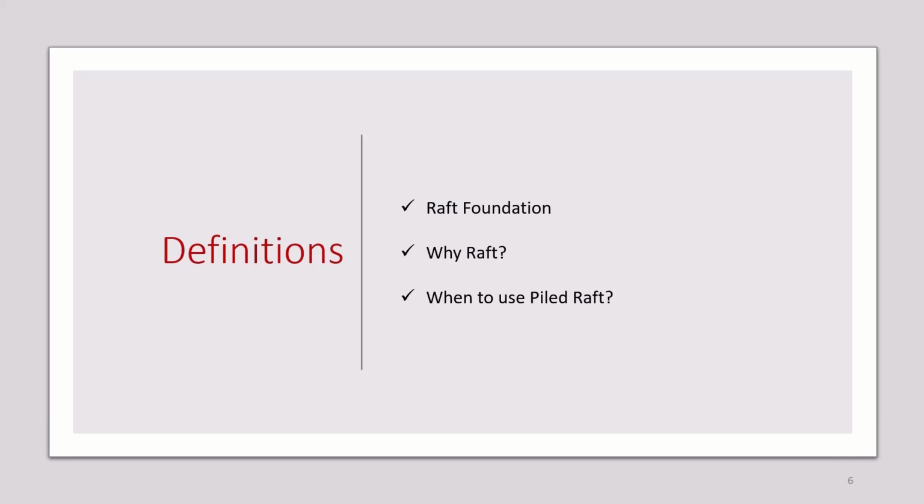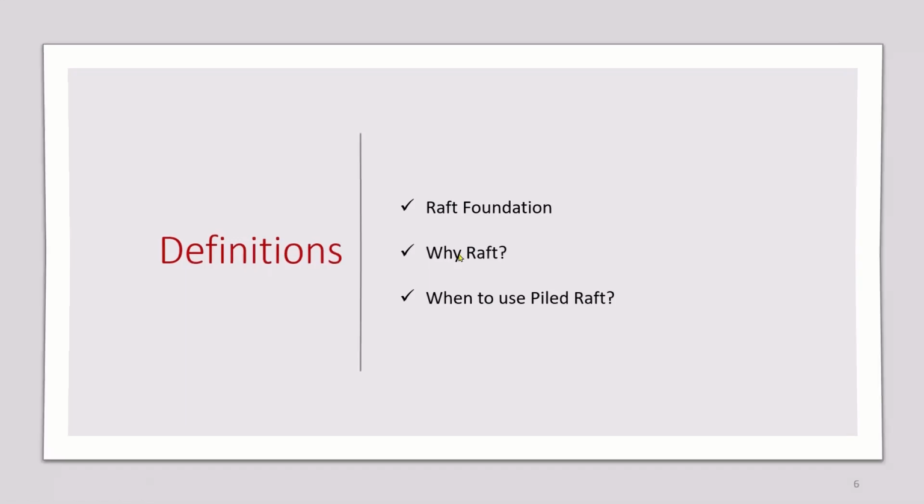It is also used when the load imposed by the superstructure is higher in magnitude. So there are kinds of structures that will necessarily require you to use raft foundations. And when the water table is higher on the construction site too, raft foundation can be adopted. It is also preferred to avoid the shear failure of the structure due to uneven settlement.